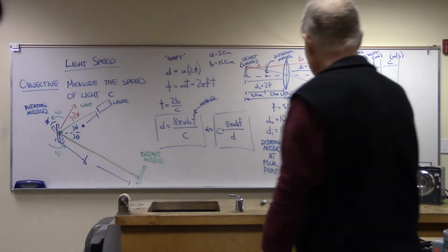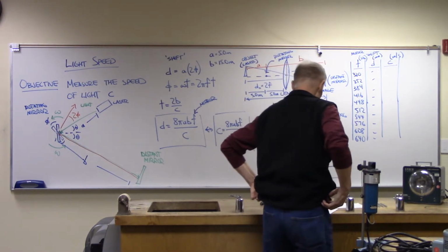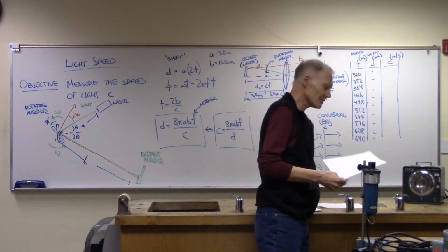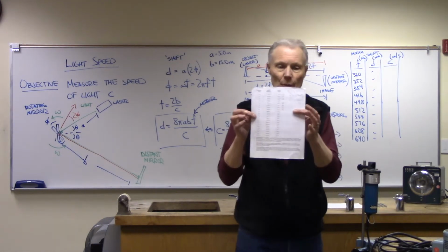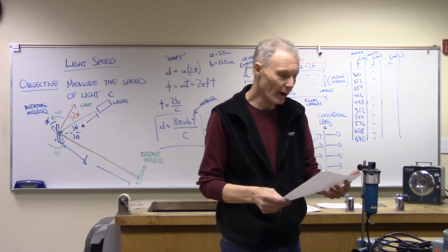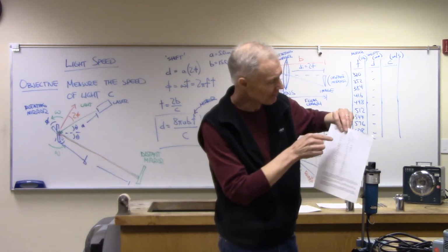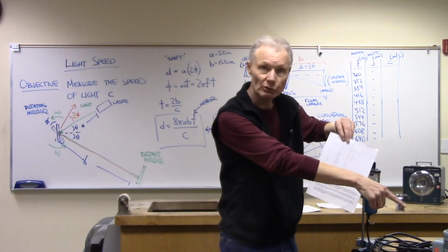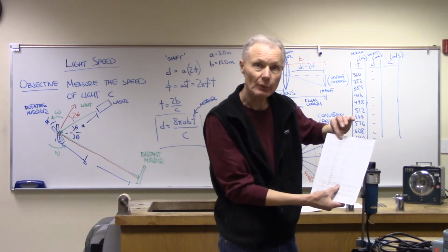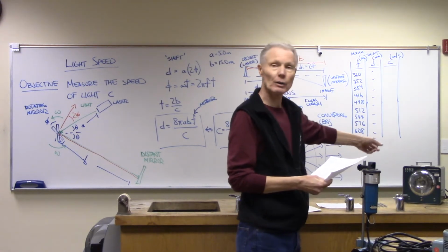So when I've carried out the strobe light calculations, we kind of go back and forth. But what I've come up with is this calibration where I've identified, at different voltages, what the motor frequency is. Now you might say, well, how do we trust the strobe light?